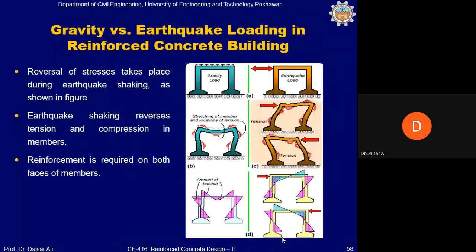However, if you do not model your infill walls in your ETABS and SAFE numerical models, then the lateral load, which is resisted in reality up to some extent by these walls, will not be taken into account. The portion of the reinforced concrete frame structure where these infill walls are situated will be resisting the lateral loads with much stiffer elements than the locations where there are no walls.